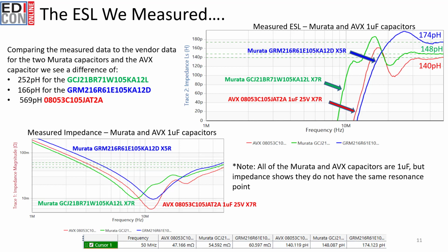caps. The last thing that I'll leave with on this slide is that after measuring all kinds of caps, special low ESR caps, there really is little difference. An 0805 package size has so much inductance, most of which is due to the size of the component. If we could make the excess inductance zero, as shown earlier when comparing the mounted capacitor to the shorted PCB mount, it would still only save 130 picohenries. And of course, we can't make it zero.